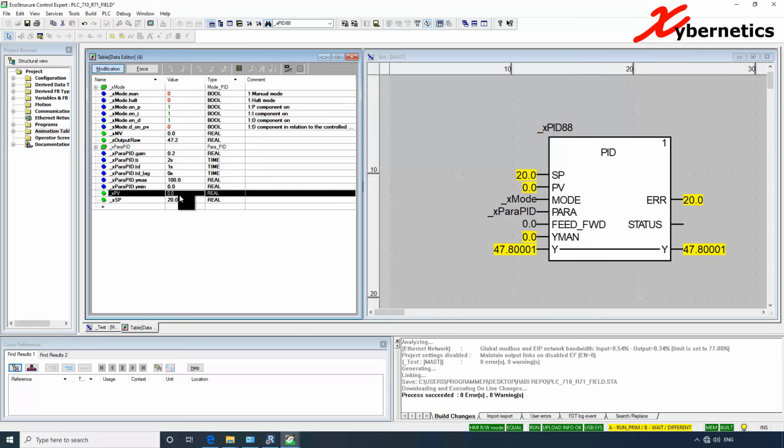If I start to taper my PV, which is the process variable, towards say 15, if I move it up to 15, you can see that the output moves a bit and it goes back to 100 again. The PID is not really tuned yet, so I'm just going to put some minimal value so at least it's not so reactive. That's part of the tuning that you can do. Still your PV is lower than your SV, that's why it always goes towards 100%. If I go close to 20, you'll see that the value is more stable now.